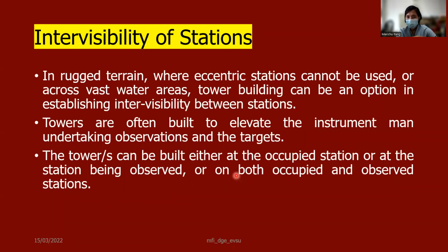So in rugged terrain where an eccentric station cannot be used, when we say eccentric station, these are the stations that we establish for the sake of those points that are impossible to occupy, so there will be another station.